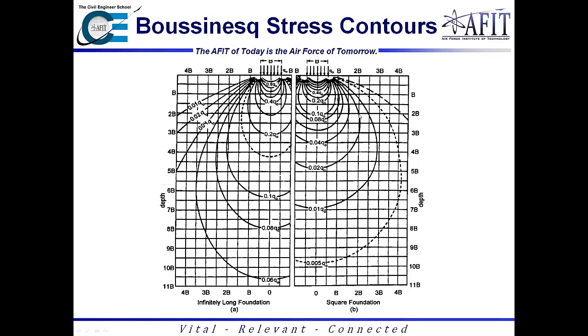And so if you do notice, like I was saying, the pressure below the actual foundation at any given height or any given depth is parabolic. So if you notice, if I'm down here at the center, I'm at about 0.06 Q naught. However, if I start moving away, I get to 0.04, 0.02, 0.01, and then 0.005 Q naught.